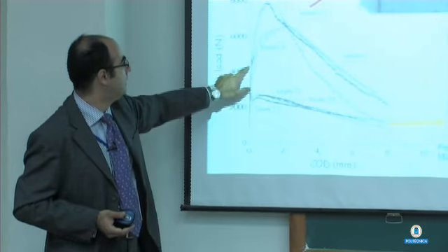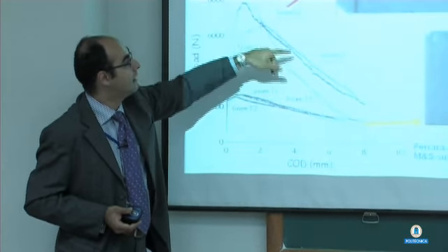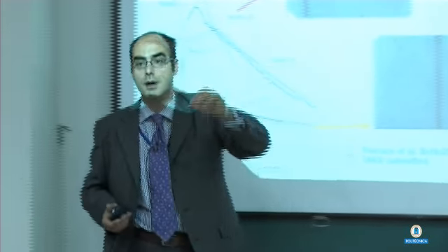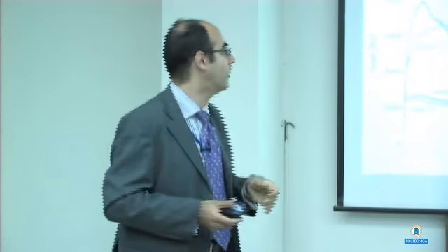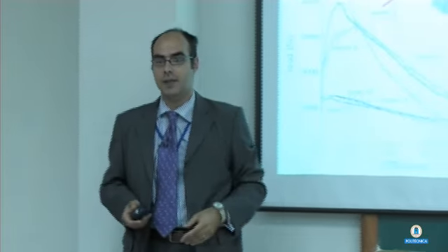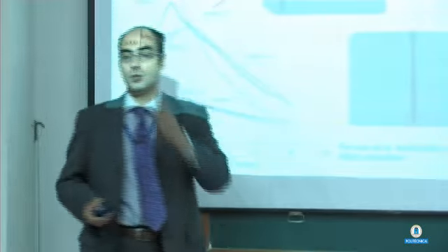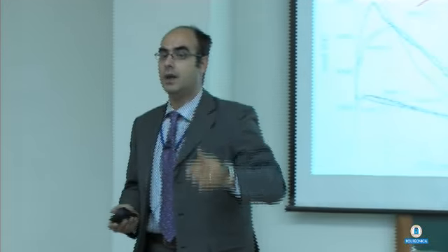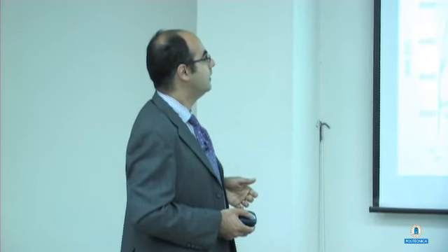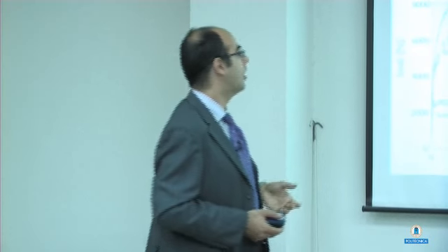While here we have a significant hardening behavior with multi-cracks. You can see here in the X-ray picture some blacker lines which show the multi-cracks which formed before the peak, and we could hear. We did not perform acoustic emissions, but we could hear during the test these multi-cracks forming. And after that, we had the localization into a major crack, and the softening behavior started. While here, we just have one major crack in the beginning, and that one went on without the formation of any other crack.